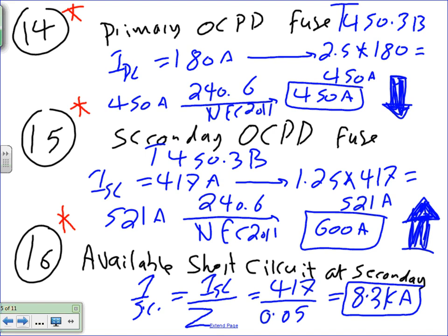As you go into the design, this is very important. It gives you an idea of the short circuit rating of the circuit breaker or the fuse, because I know the secondary circuit breaker is 600 amp, right? When we size circuit breakers, we size them based on three things. Number one is the full load amp that you need to pull out of them, the highest amp. In this case, you can pull the highest amp with 600 amp, non-continuous. Number two is the interrupting rating, how much current they can interrupt without blowing up. I need them to handle this amount, so that will be 10K. 10 is higher than this, so we're good.